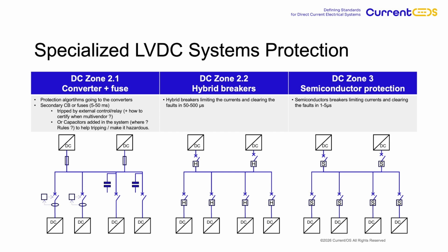These systems are intended for applications where Zones 1 to 2.2 cannot be fully contained, and where power distribution within these zones is essential. In these cases, the system should remain as confined as possible, ideally within a dedicated electrical room, and should be designed with the support of qualified experts. The use of hybrid protection devices offers certain advantages, but it also requires a more detailed system design, particularly regarding the calculation of cumulative fault currents. These calculations can become extremely complex in systems with multiple sources, especially when some sources, such as batteries, can also behave as loads at other times.